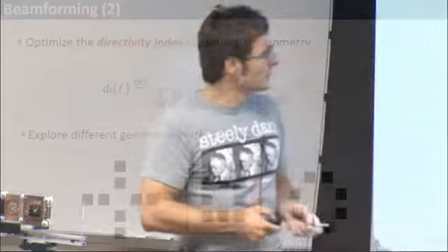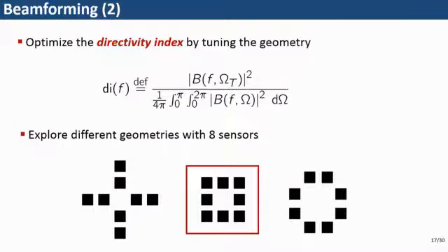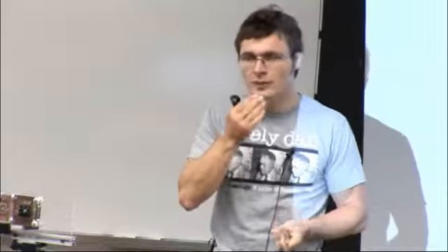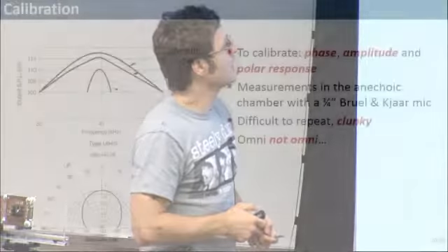If you remember how it looks, it's 3 microphones laterally and 3 microphones vertically. So with a 3 microphone array in some direction, you can't do much. We have 8. But if you want to extrapolate the performance you have in a horizontal plane, you need to square the number of microphones, okay? So for example, the performance that you get with 8 microphones horizontally, you'd get with 64 microphones in the whole space, okay? Okay, so let's go on, right?